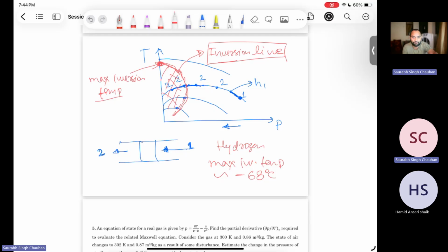If you have only fuel, then it will not burn. You also need some oxygen, an oxidizer, a fuel-air mixture, and not just that. It should be within the flammability limit. If it is outside the flammability limit, then it will not ignite. And hydrogen has quite a wide flammability limit, so from very lean to very rich, it can burn easily.